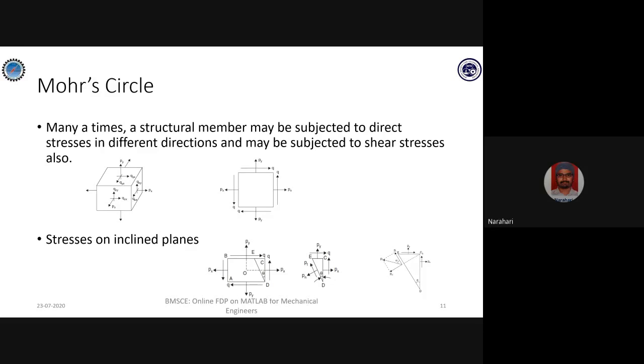Universally, we take a three-dimensional stress element, or stress tensor element, which is seen on the left-hand side. But in most problems we simplify it and say it is a plane stress element. So a plane stress element is loaded as shown in the right-side figure.